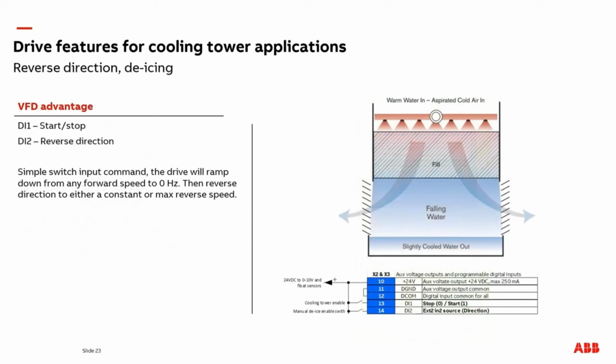In cold climates or winter operation, ice buildup may form on the outside of the air intakes. If no bypass valve is included to direct water flow to the basin or dampers to close the air intake louvers, reversing the fan direction can move warm air back out to the louvers to melt ice before returning to normal tower operation. Tower fans without a variable frequency drive won't be capable of this reverse direction option, requiring the other forms of ice prevention.